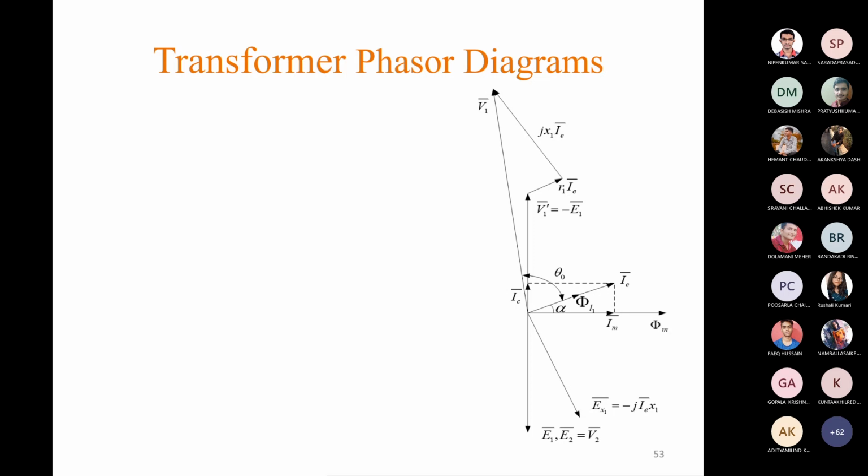Okay, so now if we want to draw a phasor diagram or equivalent circuit, then all the quantities must have the same frequency, which means for every frequency voltage we will have one phasor diagram. So to avoid such complications, in your syllabus only these 50 hertz frequency quantities are considered.